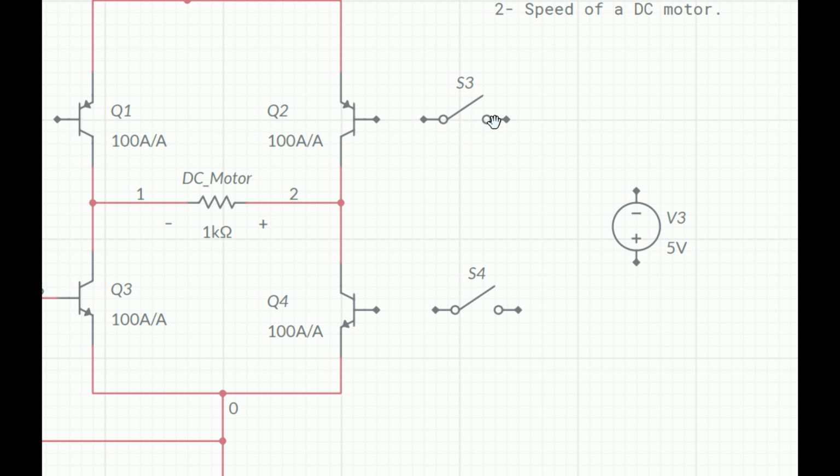Now see that I added the voltmeter over here, positive to this side and negative end to this side. Right now all the transistors are not triggering. I run the simulation, and no transistor is triggering, we don't get any voltage. Okay, negative is not connected. Bring it like this. Run the simulation: no voltage, it is just millivolts, some leakage current or voltage coming from the transistor because we have not used resistors.